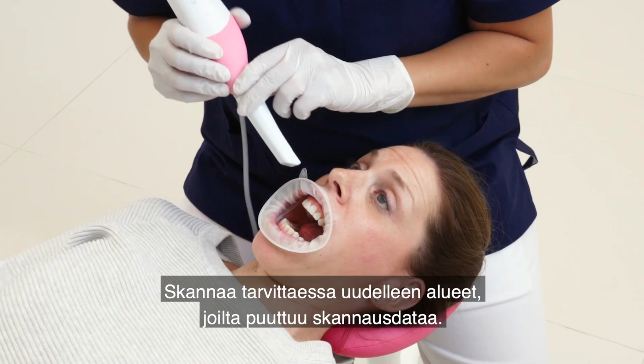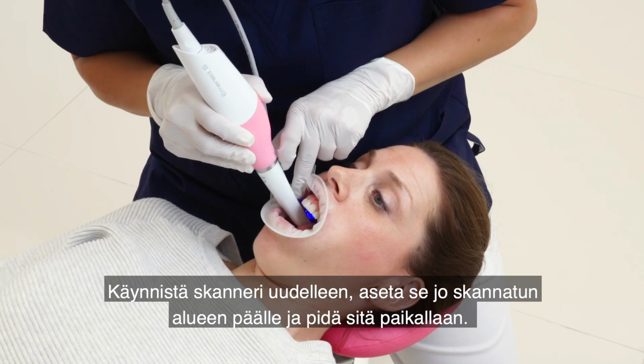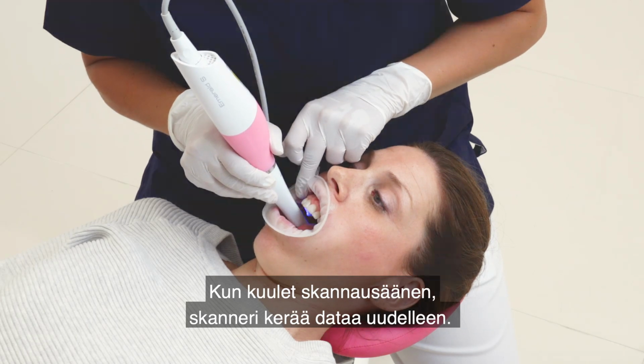If necessary, rescan any low data areas. Restart the scanner, place it over an area already scanned, and hold it still. When you hear the sound, the scanner is capturing data again.